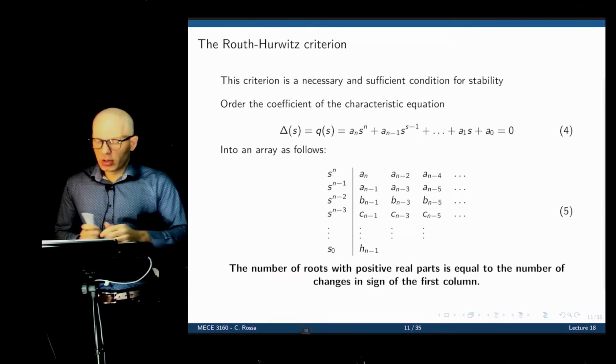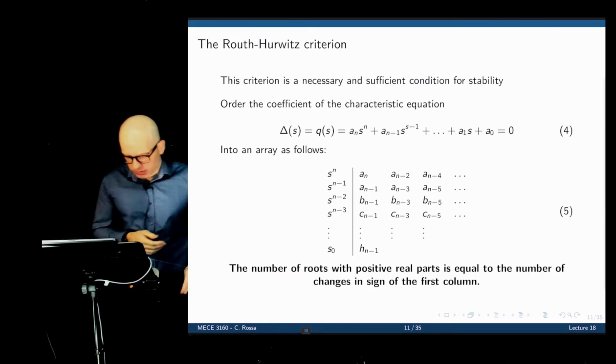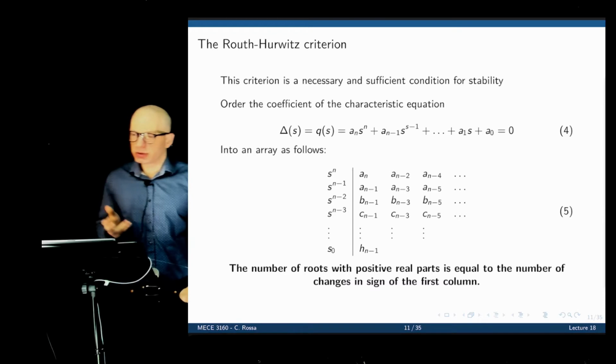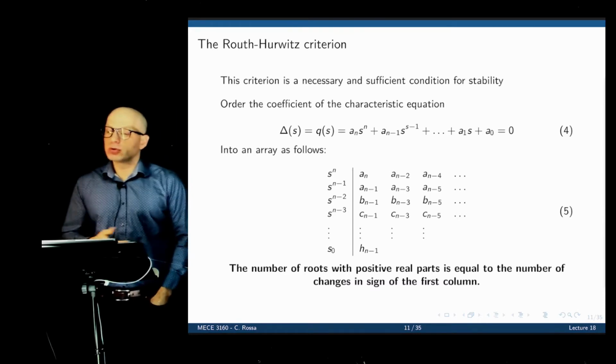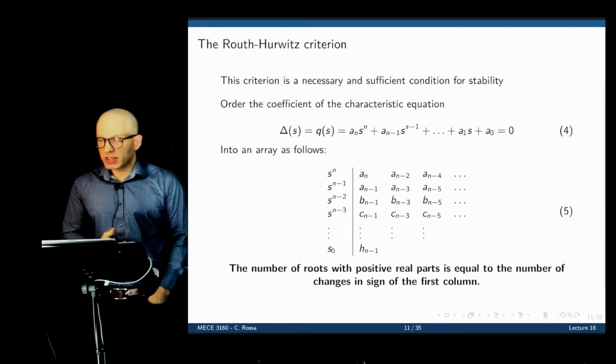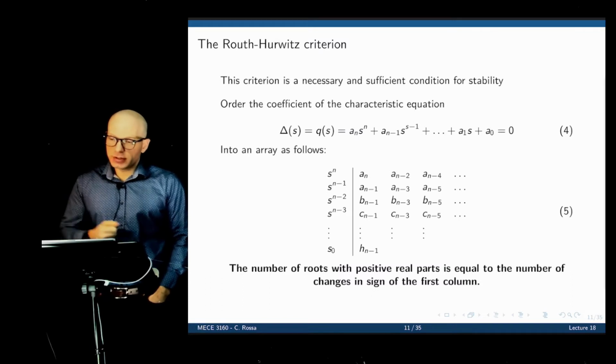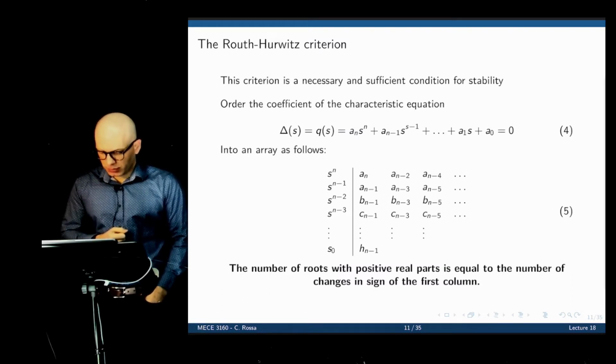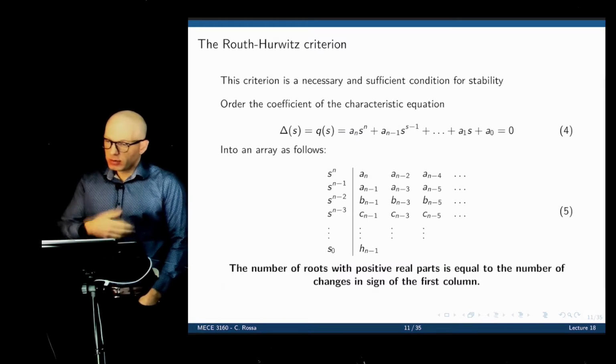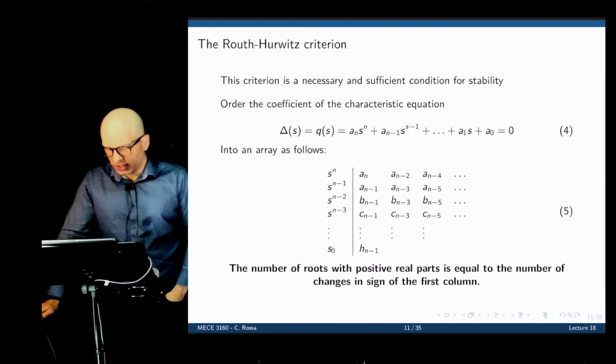No? Okay. So our job now is to assess the stability of a system. It is very simple. We just need to determine whether we have poles on the left or the right side of the S-plane, or if they are sitting on the imaginary axis. If you want the system to be stable, the poles need to be on the left side.